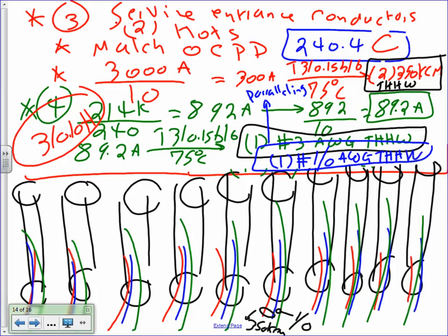I need somebody to give me a thumbs up, Chad. We fully understand what we have done. Now look at that. You could have carried 350 and lost the project, Joe, when you bid on it, right? Imagine 350, guys. Look at this, 350 times 10. 10 conductors, 350, multiplied by at least probably 100 feet. See how much copper you did versus what? 1 aught.